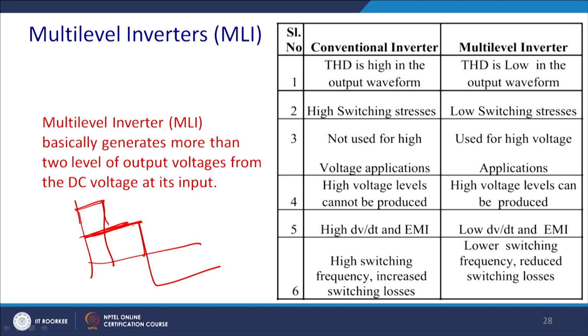To match this volt area, essentially you will inject more and more harmonics. But let us consider a simple case: when you switch on, it gives 12 volt, but you require 5 volt instantaneously. So, you will apply 12 volt for a small interval of time, and the rest of the time you will apply 0, and thus you say that actually this volt area matches.